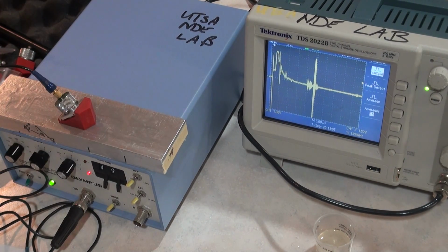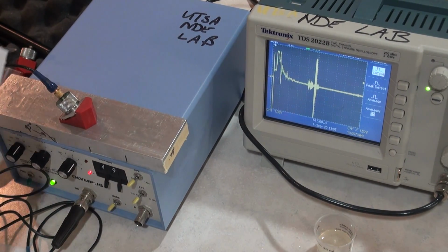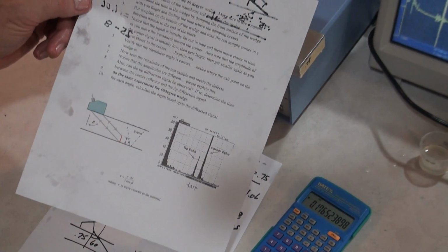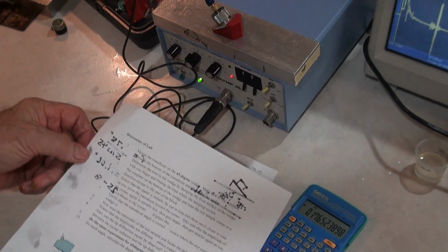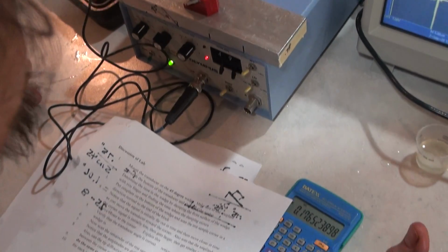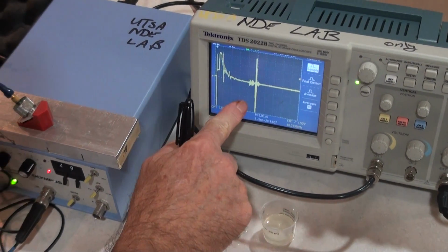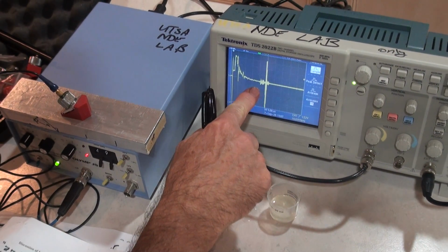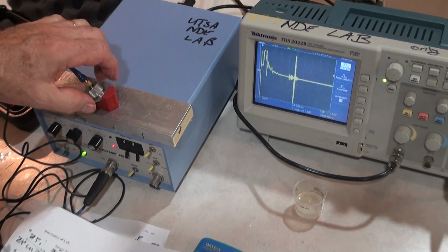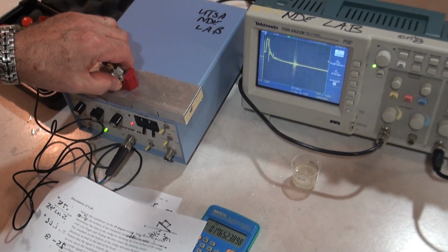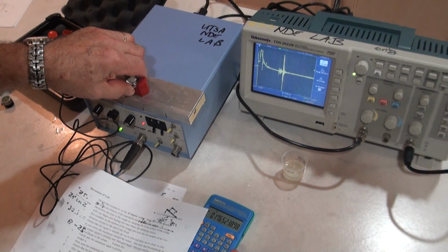So that means it's deeper. This calculation now is bigger, so delta t is bigger, so the defect is bigger. And if in this case we use the time of about 4 microseconds, at 5 microseconds per division, so it's almost 4 microseconds, that should give us the height of the defect.